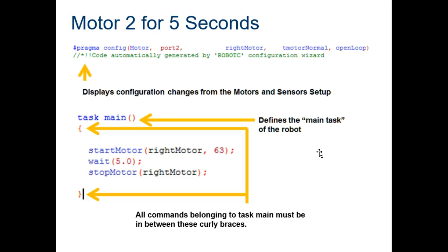Let's say you wanted to go really slow, so you put in a 6 instead of 63, and it may or may not work. These motors have what is referred to as a deadband. It is telling the motor to do something and sends a small amount of current, but it's not enough to get the motor started running. That's important to be aware of. There is a point where the motor will stop working. And here's another frustrating thing: it's different for every motor. Some are easier to turn, so they work under lower current conditions, and some are harder to turn.